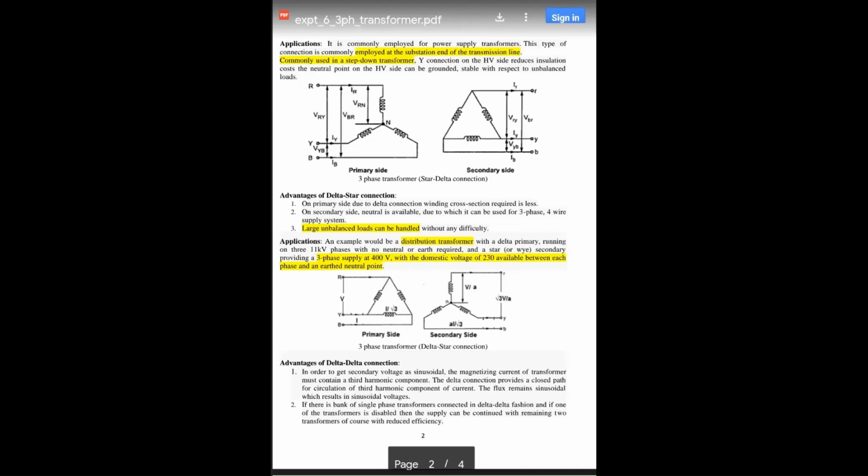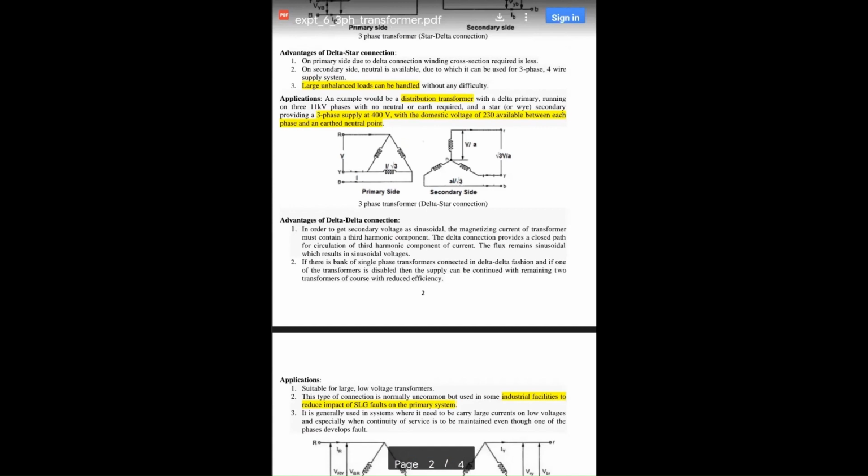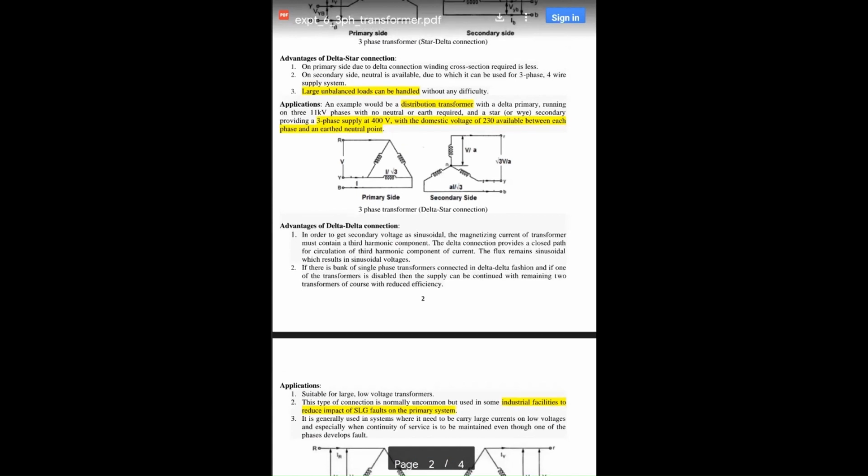Now, when we do this experiment in the lab, we set the voltage with the help of an auto transformer and measure these line voltages physically, using the voltmeters which are connected to the panel. Based on the voltage which is given to us, we also calculate the values numerically. Then we can compare whether there is some minor difference or not. An error of 1%, 2% is permissible. This is what we do and verify in the lab.